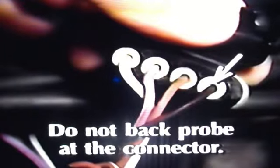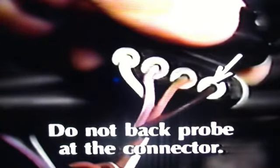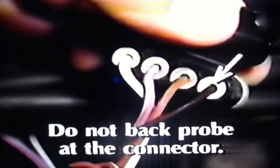Weather pack seals also help prevent voltage-reducing situations. Essentially, weather pack seals are moisture-proof silicone seals which keep the circuit intact. They're found in the connector where the wires run into it and where the connection is made. These seals, combined with the positive latch, are usually enough to prevent any problems, unless, of course, they've been tampered with. Tampering can mean a lot of different things. It could occur from accidental damage in the service bay, or even from a customer working on his car himself. In any event, when doing system voltage checks, be careful not to back probe at the connector, or you could accidentally tear up the seal and allow damaging moisture to defeat the system performance.